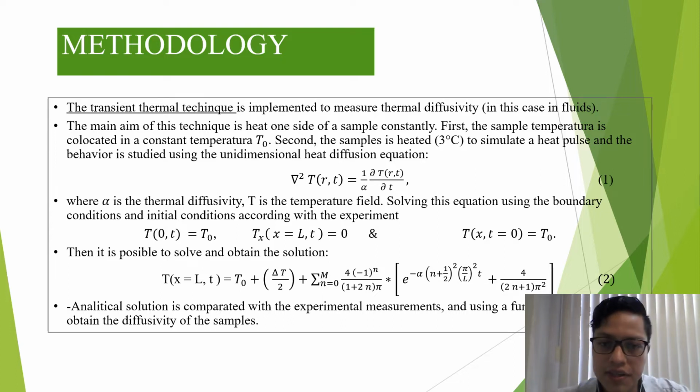The transient thermal technique is implemented to measure thermal diffusivity, in this case of fluids. The main aim of this technique is to heat one side of the sample constantly. First, the sample is set at a constant temperature, T0. Second, the sample is heated, in our experiment by 3 degrees Celsius, to simulate a heat pulse, and the behavior is studied using the unidimensional heat